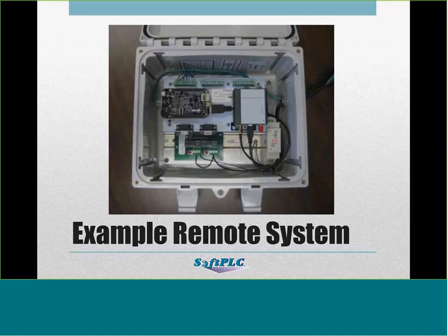So if you've got a remote system that's powered by a solar panel, you can have the PLC provide warnings and alarms when the batteries are not functioning properly or there hasn't been enough sunlight or whatever. We also have here a cell modem, so that we can get to the cloud. This whole system, without the solar panel itself, is less than $800. So it's a very low-cost way to have a very powerful system that is bidirectional: cloud-based access, data logging, control, HMI, everything.